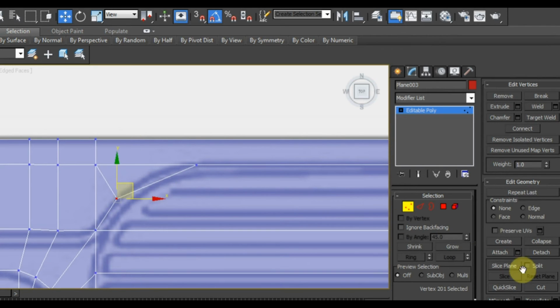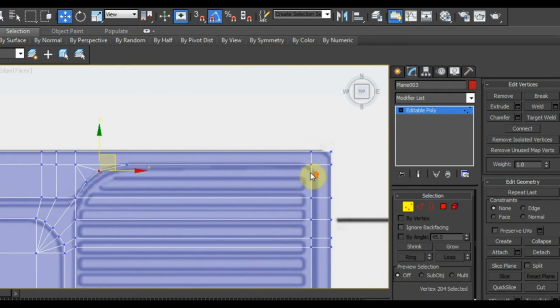And what we could do is cut that to there, to there, and turn off cut, and we can move that around. Now, as I said, it's not ideal the way I've done that, because we've got triangles, and it's best to try and avoid the triangular shapes if you can. There are different ways to go about doing that, I'm just doing it for a quick effect, to see how you can do that.